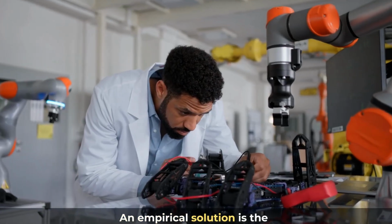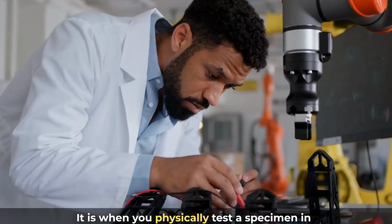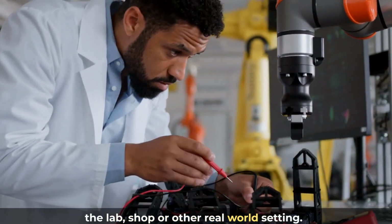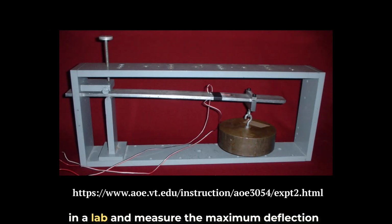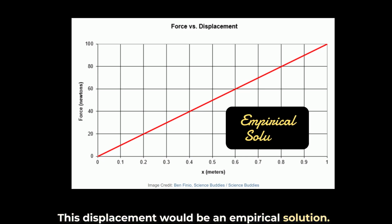An empirical solution is the same as an experimental solution. It is when you physically test a specimen in the lab, shop, or other real-world setting. Going back to our cantilever beam example, one could perform a load test on a beam in a lab and measure the maximum deflection using strain gauges or by some other means. This displacement would be an empirical solution.